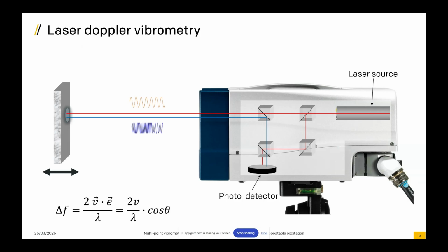So looking at the change in wavelength between the reference signal and the returning signal, we're able to decode velocity from that. The reason that the light is shifted in wavelength is because the vibrating object, which it reflects off of, imparts or removes energy from the laser itself. So that's the Doppler shift of light. And that's ultimately how we get velocity out of our systems.